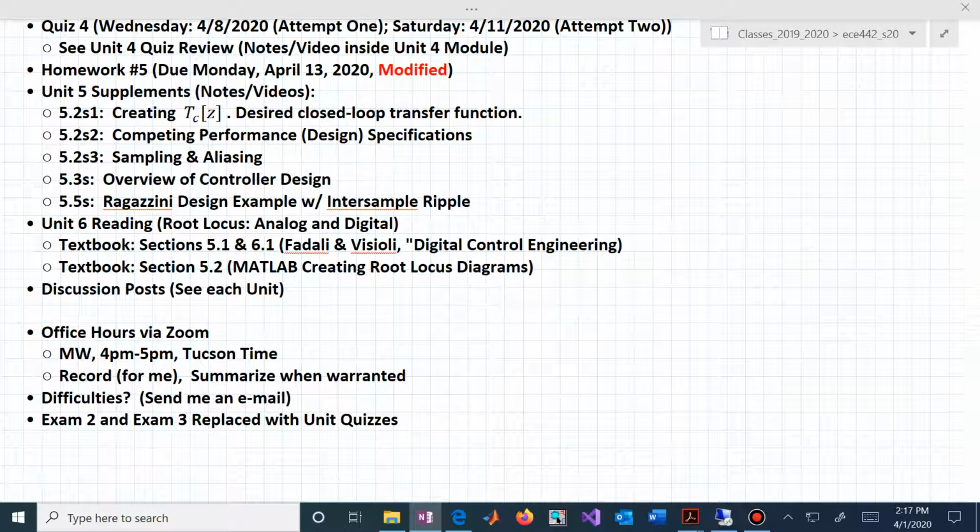Likewise, we have our breakfast cereal shapes in the Z-plane. We have our hearts that are helping us better understand settling time behavior. Our hearts, or logarithmic spirals, give us an insight into the percent overshoot behavior, and these angles that our complex poles make with the positive real axis in the Z-plane, those angles or wedge shapes determine the peak time behavior.